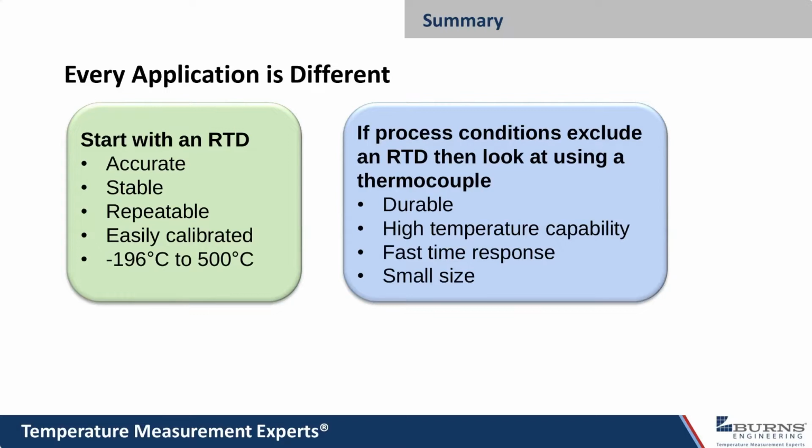So if we say we're going to use an RTD, we'll try to find reasons to maybe exclude using it. Some of those are going to be durability. The thermocouple wins the durability contest every time. Some RTDs are made specifically for heavy duty applications, but still the thermocouple is going to have the advantage there.